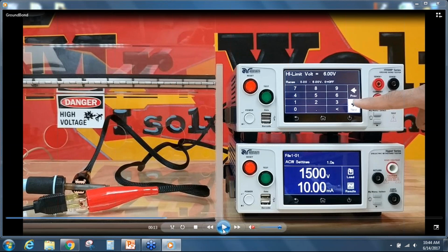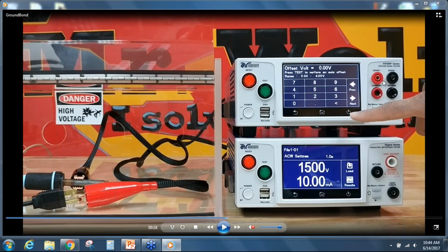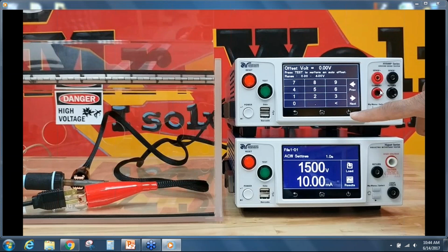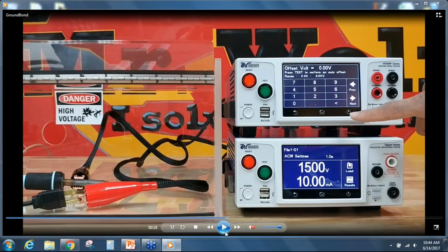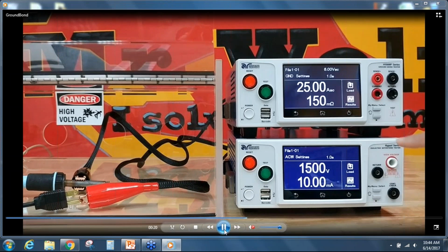So the standard will specifically call out for a high limit on the voltage drop across your DUT. Low limit is zeroed out for this. And then offset, since we have a 4-wire connection, if you take a look at our product, it has a sense plus connection and a sense minus connection with current and return jacks that make this a 4-wire measurement. It's more accurate compared to a 2-wire measurement, as the instrument has capability of measuring voltage all the way down to the DUT.